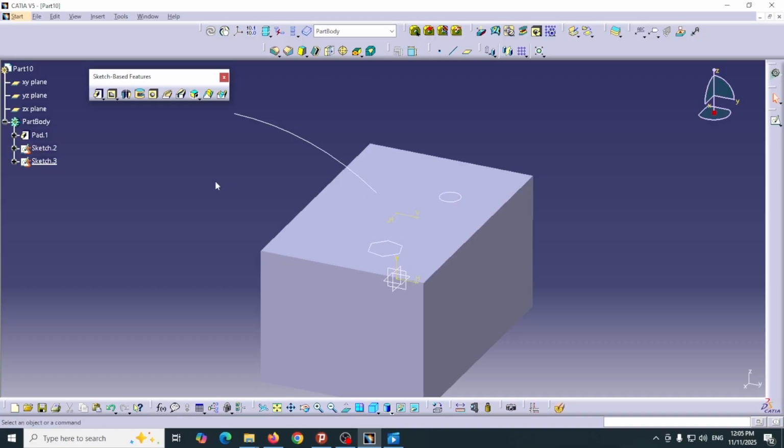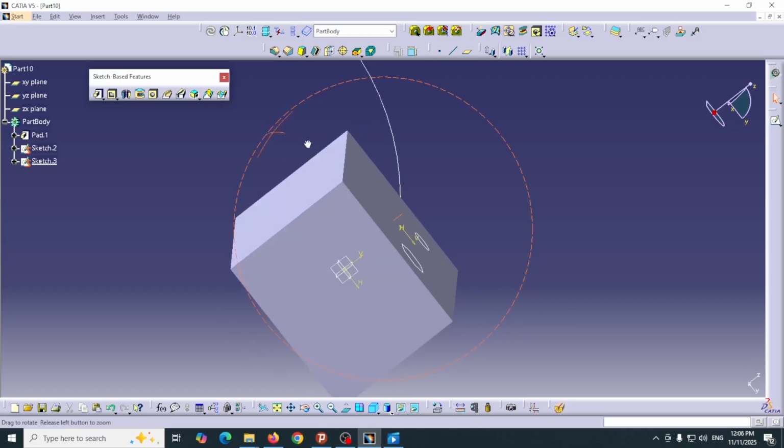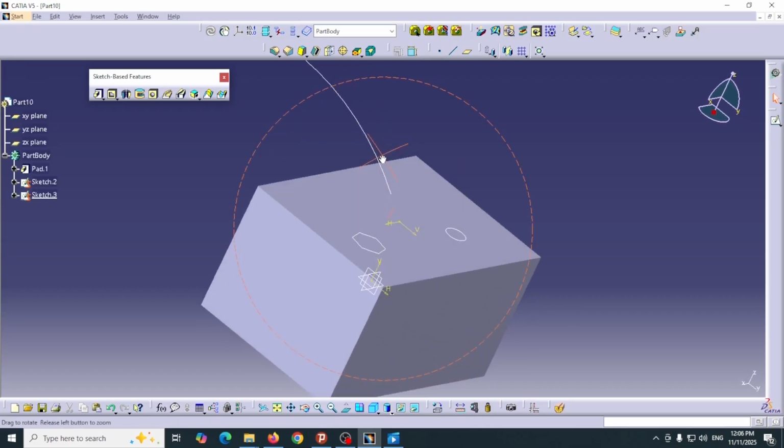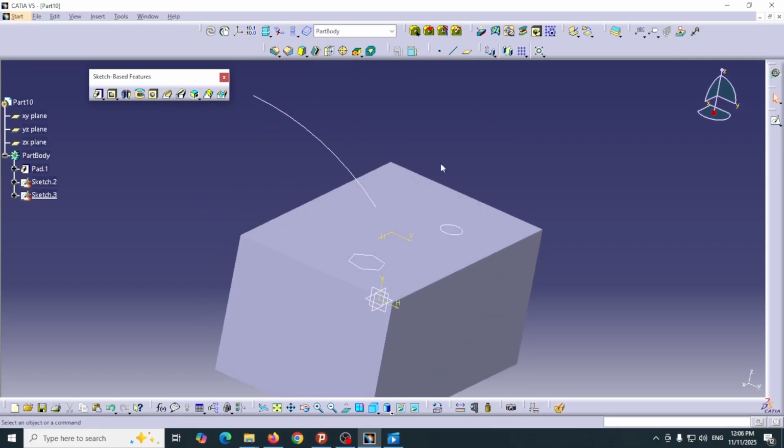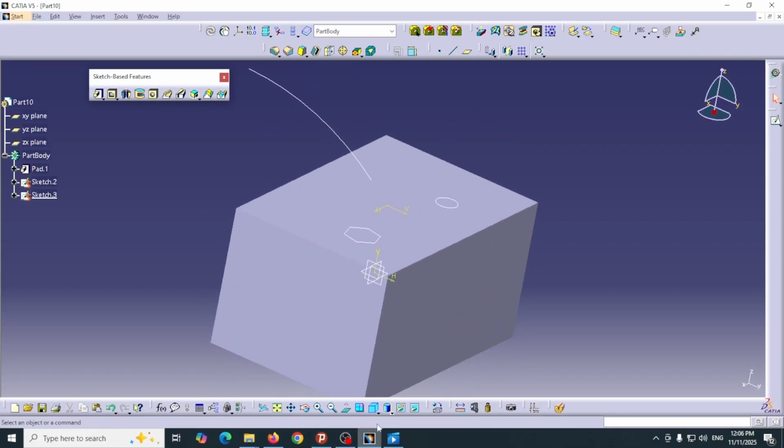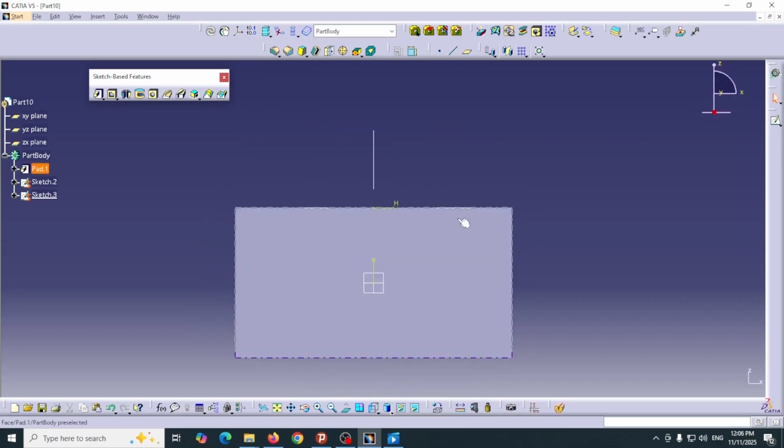We have two profiles that are in one sketch and an arc path in another sketch. Since the two circular and hexagonal profiles are drawn in one sketch, they are recognized as a single sketch. The curved path is on a plane perpendicular to the surface of the profiles. The path does not start from the center of either profile.